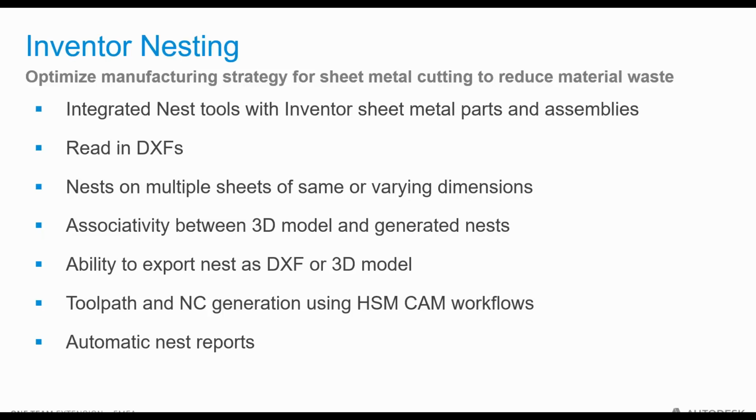You also have the ability at the end to export the nest as a DXF or a 3D model for visualization purposes as well. So if you had an assembly, you could use simple iLogic, and you could create individual DXFs of parts as well. So it's pretty much a very handy tool to have if you're looking to optimize your nesting environment.